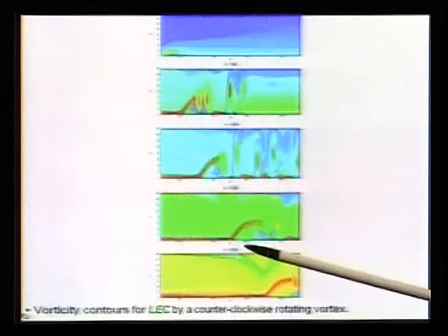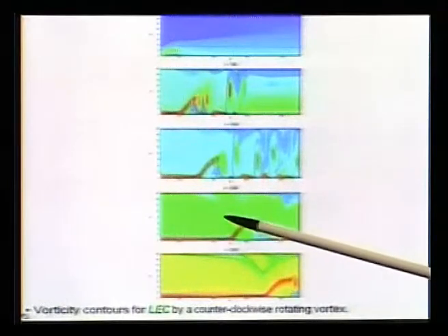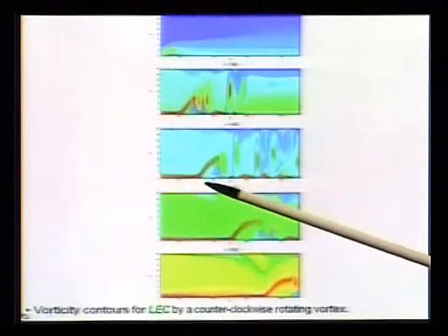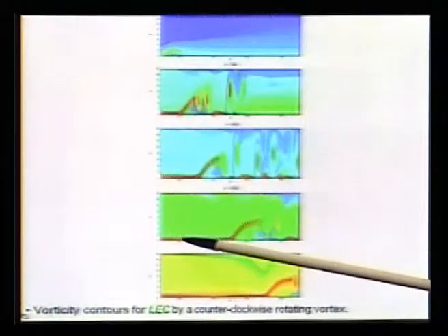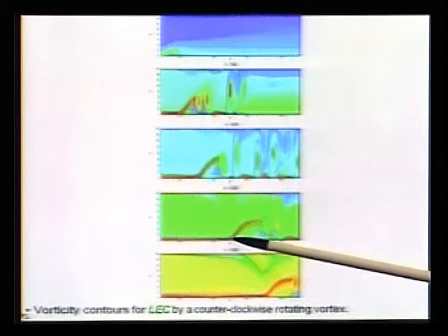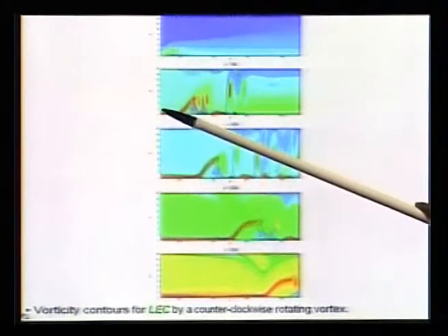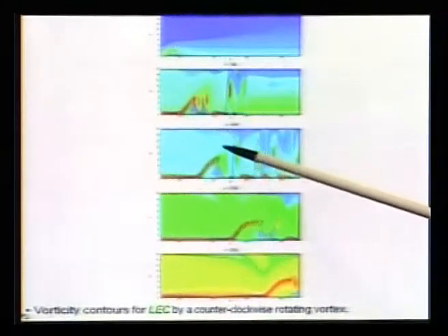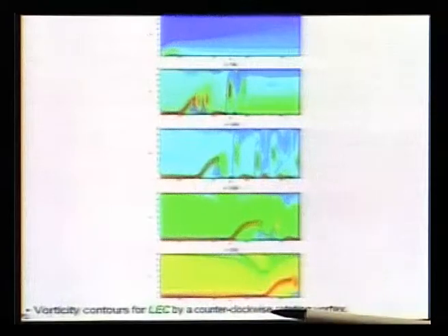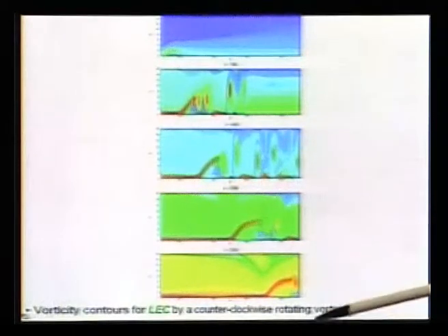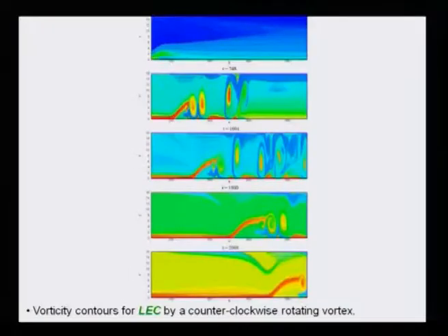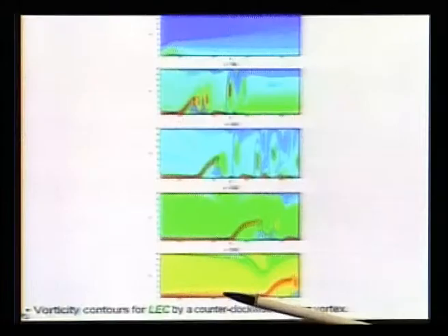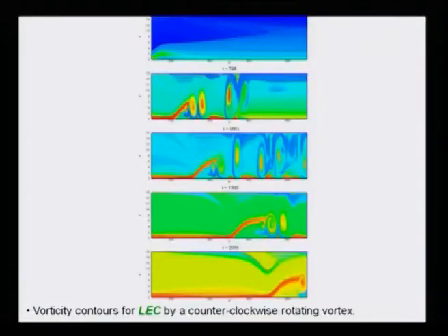We see that very clearly, that here, well, it was getting affected here. Here also you could see the vortex is somewhere here. There is a little bit of thinning down, and here it is. You can see it has thinned down a little more, and here the thinning down is marginal. But as time progresses, you can see this is the trace of the free stream vortex. That is why we did not even mark it by an arrow, if I wanted you to understand that. But here in this part of the shear layer, it has acted over a longer period, and that cumulative effect shows a significant thinning down of the boundary layer.